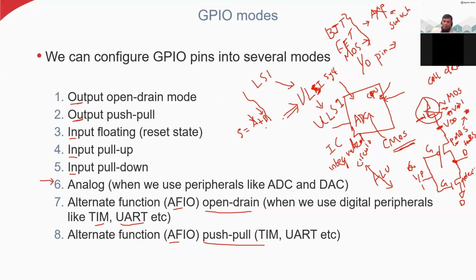And then you have to do the synthesis. Of course, you have to do the simulation and check. You can apply the clock signals and everything is synchronized, and then you can check the output. After the simulation, you have to go through another process. Synthesis means this program, and there are so many tools for this synthesis.